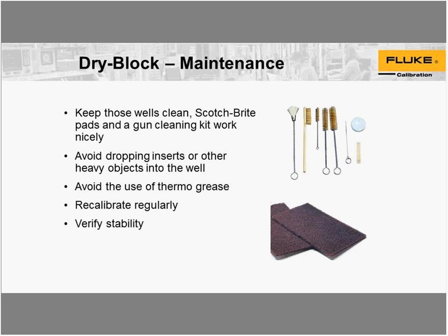If you don't clean it out regularly, it becomes a glue, and then you run the risk of gluing your insert or probe to the unit. And on the maintenance, recalibrate and verify them regularly so you're not overlooking a potential issue in the process that may cause a recall or error potential.